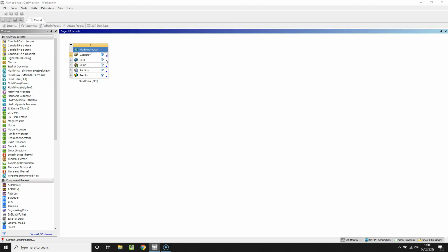We're going to begin by sketching an Ahmed body, sketching the domain, and then we're going to apply some geometry changes and a parameter set to the Ahmed body. From there we'll run a simulation, we'll create an expression in CFD Post, and from there apply the optimization to our geometry.